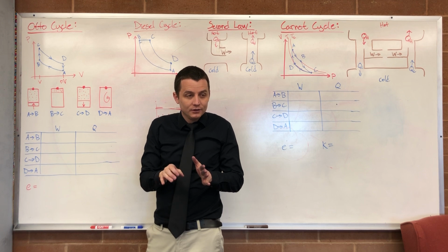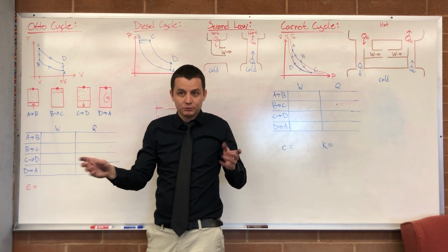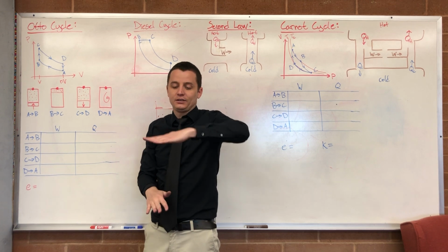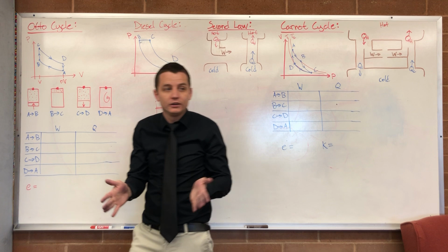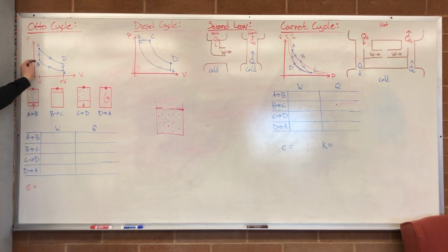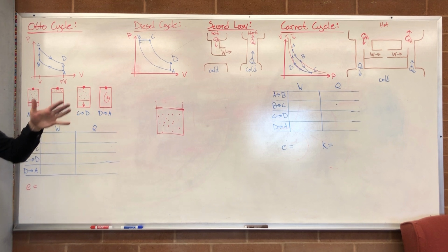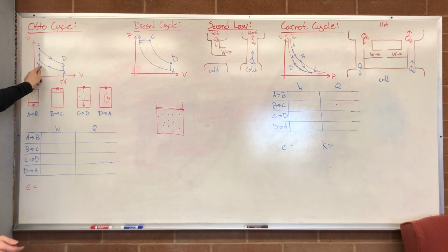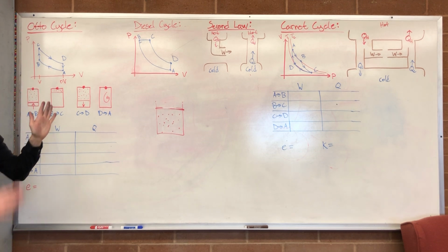Why is it really quick? Why doesn't it just sit there and burn? It's going to burn up all the gas fumes. It's not like when you have liquid gas and you're burning off the top. It's gas fumes, so all the gas fumes are going to burn very quick, very sudden. So there's a mini explosion, and it happens so quickly that the piston can't suddenly expand with it. Piston expanding takes time. This explosion is very quick. What that's ultimately going to do is cause the temperature to shoot up inside the piston. It's going to suddenly get really hot.